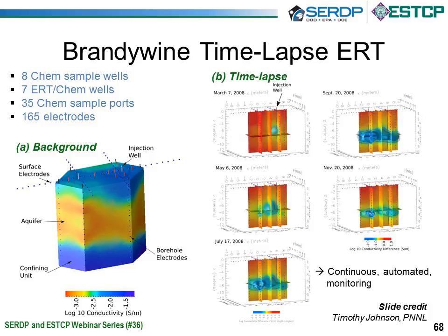So here over on the left, I'm showing the background characterization image, and it reveals the overall geological and geochemical setting. So the image is consistent with what was found during the well installation. So we can see a high conductivity deep zone shown as the confining unit, a low conductivity intermediate zone of coarse grained sands, and a shallow intermediate conductivity zone corresponding to fine sands and silts.